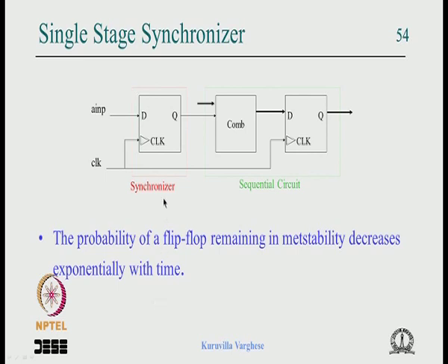That means that if this asynchronous input violates the setup time or hold time, and the flip flop gets into metastability, as the time passes the chances of it coming out of metastability, it is a probability, are higher and higher. As you give one nanosecond extra, the chances are more. You give it more time, you have more chances of it coming out of the metastability.